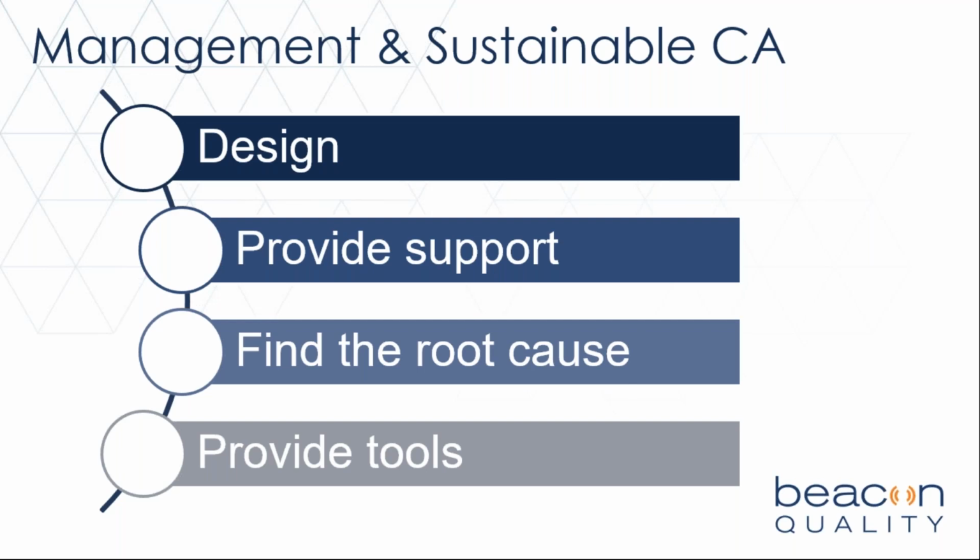the right way. A good corrective action in manufacturing is if you use your FMEA and Poka-Yoke and error proof, you will have a sustainable corrective action. Training is great, but 80% of the people get trained and 20% of the product will still escape. So always have checks and balances in place.